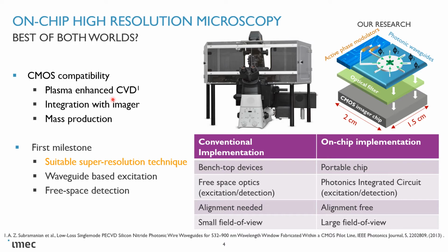This technique uses relatively low processing temperatures, which makes the full process CMOS compatible, and in turn, it makes it possible to integrate PICs on top of a CMOS imager chip. Before going on to the full integrated solution, we aim to have an intermediate step with an imaging device that utilizes waveguide-based excitation and free space detection through an ordinary microscope objective. This will be the first milestone in our research.